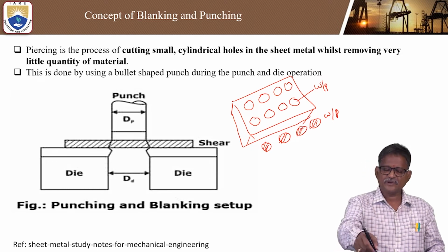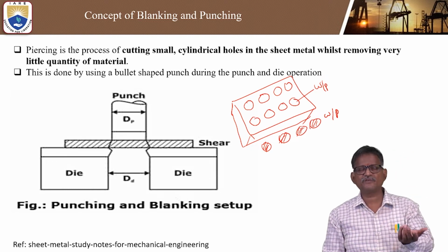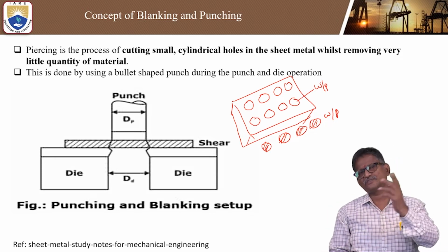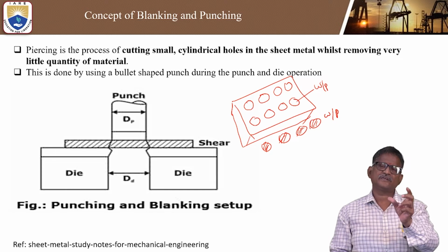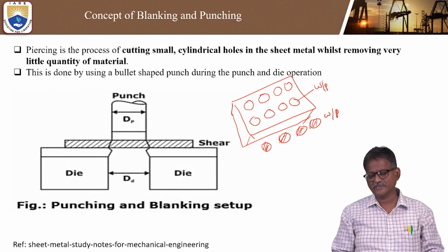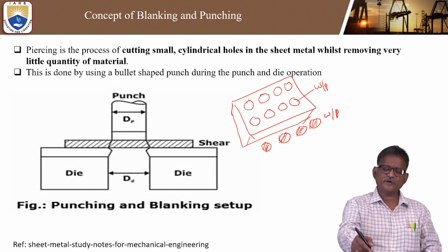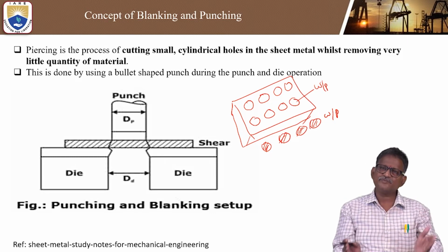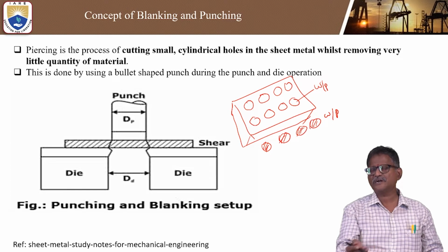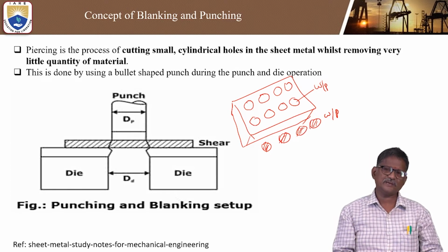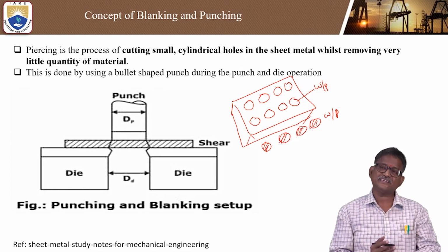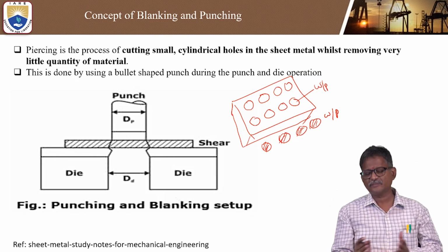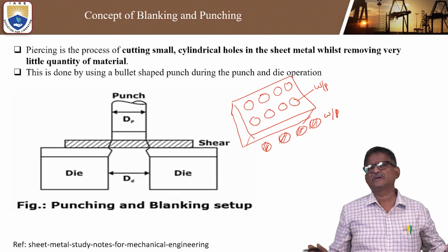Whenever you apply the tool, you can use different types of process, either a simple mechanical press, a screw press, or some more important type of hydraulic press. When you apply the force or pressure, that exact stock can be removed. It comes under the cold working process because the metal is not heated here. Just by punching, we separate the part from the sheet.